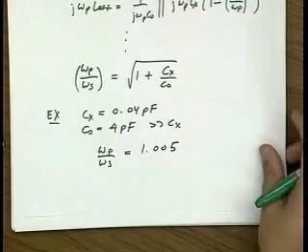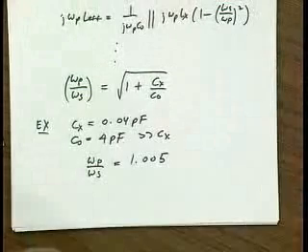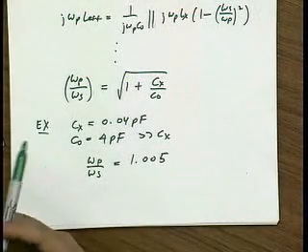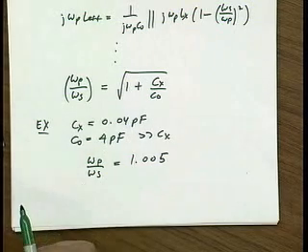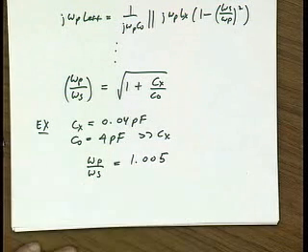All right. So let's actually look at the, yeah, so one way to choose it is to actually look at the manufacturer's data sheet, and they tell you if you want to hit this frequency, which is some very well-known reference frequency, you should choose an external capacitance of, let's say, 1 picofarad. So you would design a circuit that loads it with 1 picofarad, and you'll hit that reference frequency.